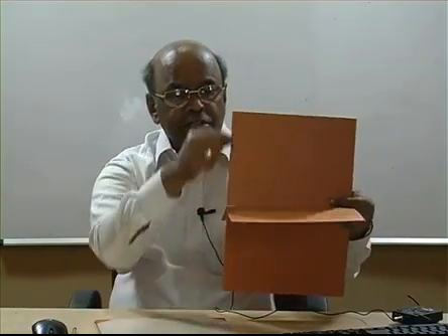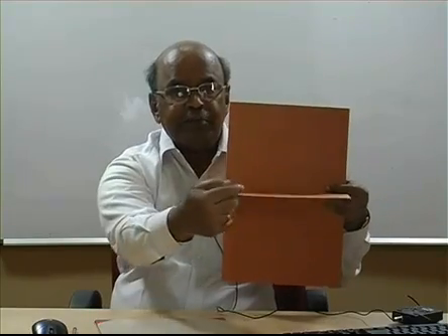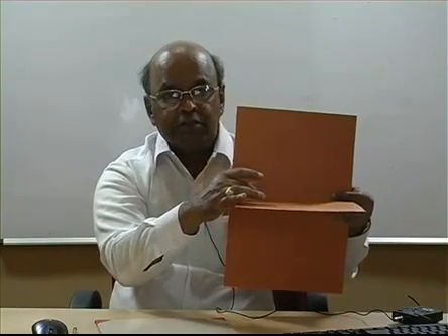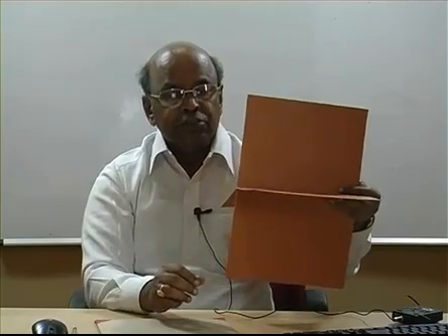How you name the two different projections obtained on two different planes. Okay. So having got these four quadrants, our drawing sheet is a single plane. If you want to represent any drawing, that is two different projections of an object on the drawing sheet, you cannot have a vertical plane and a horizontal plane. Our drawing sheet is on a single plane. So for that, you see this mechanism, how these two planes are made into a single plane. This is a horizontal plane, this is a vertical plane, and when you are seeing from your side, this is first quadrant, and this is second, third, fourth. So always remember,